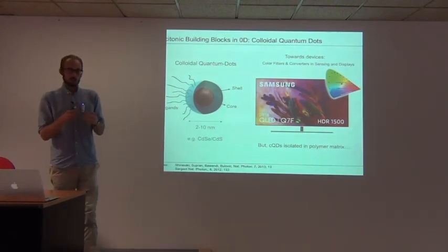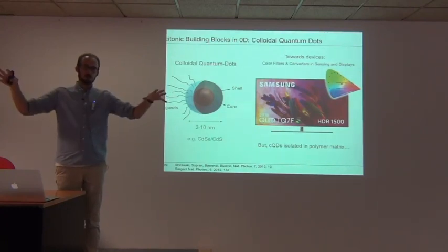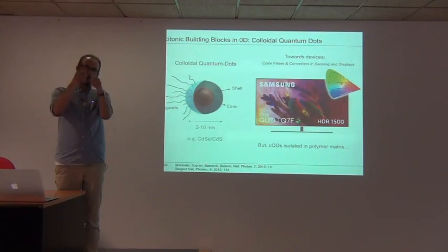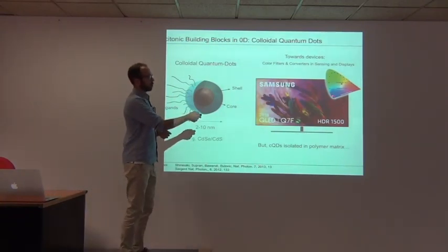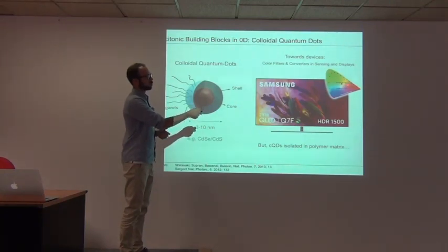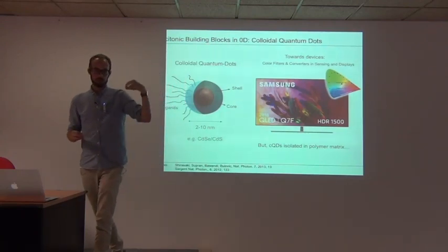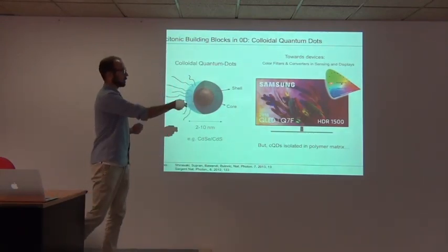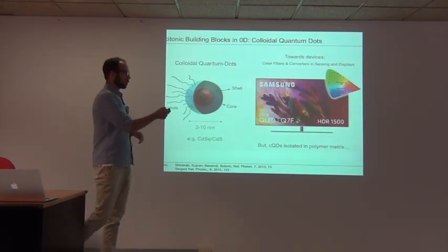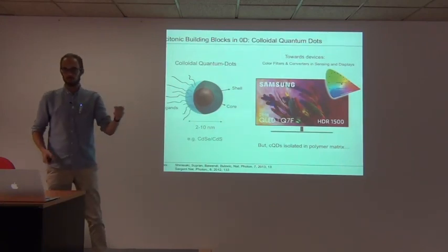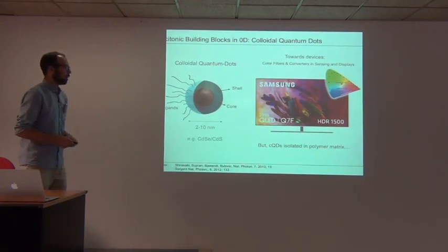Basically what they're doing here is they're substituting the organic light emitters, which have a relatively broad emission spectrum, for quantum dot emitters, which have a much sharper emission spectrum. And what you can do then, if you have these sharp emission features of blue, green, and red, is create colors that have much higher purity than in the case of organic. So you can basically, in these kind of CIE diagrams, stretch out your color gamut, as it's called, and create redder reds, greener greens, and bluer blues. So much for the sales pitch.